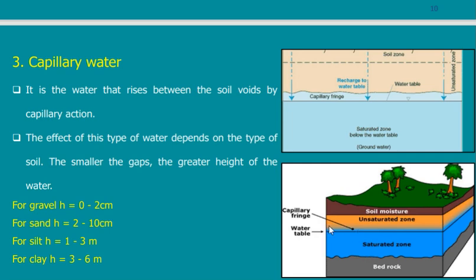So it is above. If I now get workers and I dig here a big hole, water in this hole will be leveled. Of course, once I remove the soil, it will be removed, but water will still be there and will return to reach a certain level. Which level will it reach? Will it reach the level of the water table or the level of the capillary fringe? Water table, this is correct. Why?